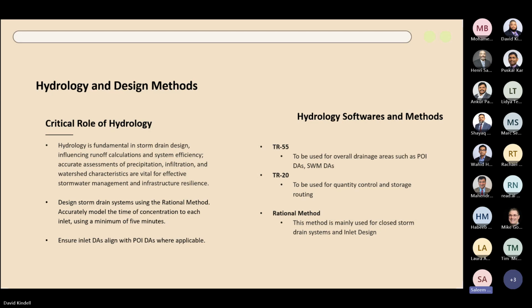It's a good discussion. So TR55 is mostly used in our design calculation if there is a small drainage area of 10 acres, a combination of roadway and pervious area, and a small stream is going through. We want to know the time of concentration so that we can design the inlet, because contribution is from the houses too. TR55 will help find the time of concentration there, and that could be used in the rational method because that needs the input too. So TR55 and the rational formula are sometimes really interconnected.